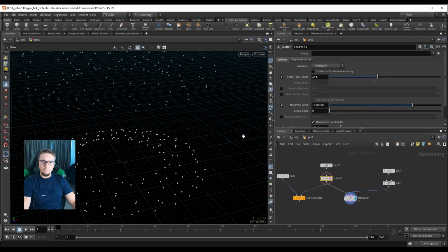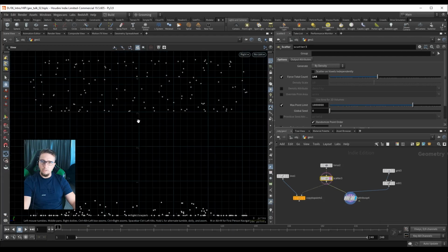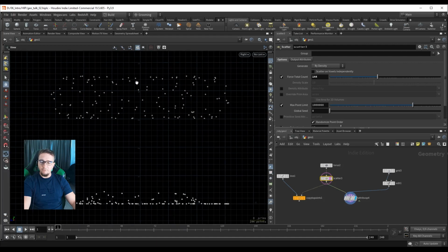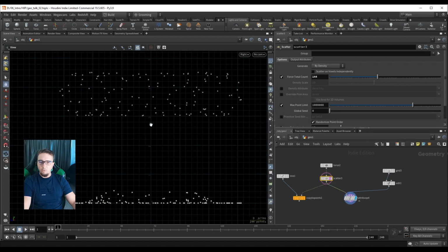And if I go up and template the scatter, we can preview where our points started. And if I go in an orthographic view, so our right view, we can see that the difference between this and our geometry is roughly 5 units. So we can see there's a 5 here, and we need our rays to reach all the way up to this value here. So the ray has to be big enough in order to reach the geometry.